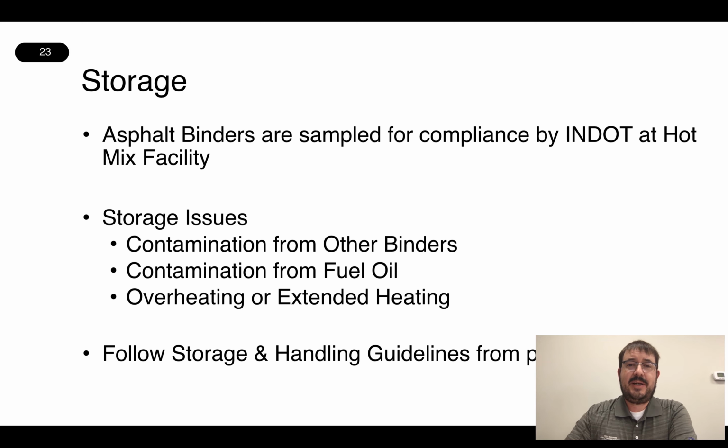Storage of asphalt binders is the next topic we're going to cover. Asphalt binders are sampled for compliance by INDOT at hot mix asphalt facilities. Some critical storage issues always are related to or could come from contamination. And contamination can occur from a number of different sources. Contamination can occur by combining different binders together. It can also be a contamination from fuel oil.